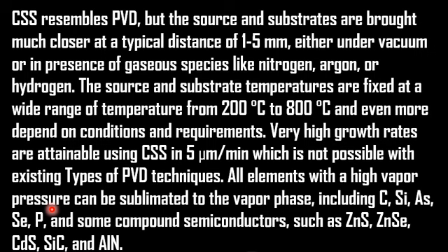So you can basically deposit a broad range of elements, and you can prepare thin films of a broad range of materials by using closed space sublimation. Some of the common elements which we can deposit are carbon, aluminium, arsenic, antimony, selenium, phosphorus, etc. However, I personally prepare zinc telluride, zinc selenide, cadmium telluride, and cadmium selenide thin films by using this process.